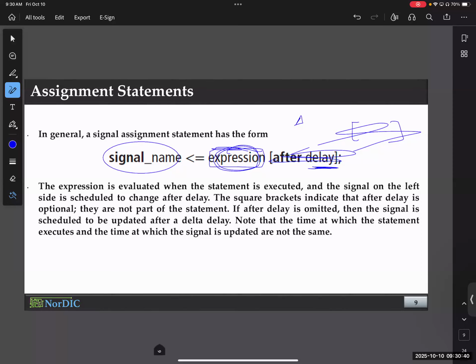And I'm also responsible for characterizing. What do I mean by characterizing? When we design these circuits, we simulate them and we also implement them in hardware. We test them, we measure their delay, we measure their performance, there are different sets of parameters that we have to report. And imagine when I report the delay, if you provide an input to this multiplexer, you get the output after 10 nanoseconds. So I already get these numbers from characterization.